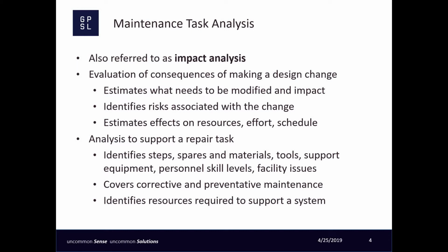Now, you can continue to use a tool in Windchill called the Impact Analysis Report to perform MTA for engineering changes. What this means is when you have a potential engineering change upstream, you are able to leverage the digital thread between your data in Windchill to see how it impacts service content downstream. This allows you to estimate the level of effort in a full product lifecycle chain to fully execute a change. When you know how many document sections and illustrations will need to be updated, you can add that estimate into the effort for the engineering change itself.